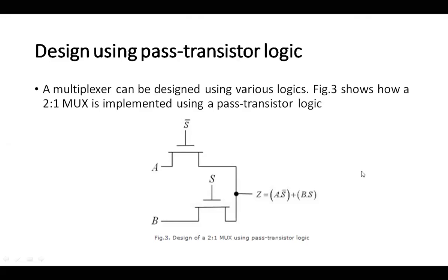That's because N type means majority is what? Electrons, right? Electrons are much faster than holes. They are lighter than holes, so if they are lighter, they can propagate fast. That's the reason we use N type of transistors, because the majority carriers are electrons. N type means electrons, electrons means less dense, less dense means fast. So I want something which works out fast. Understood?